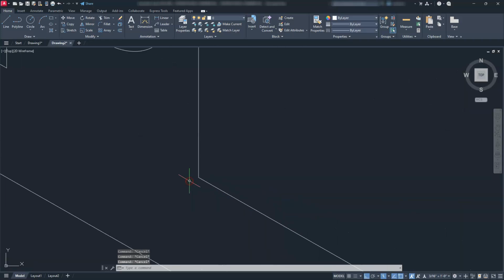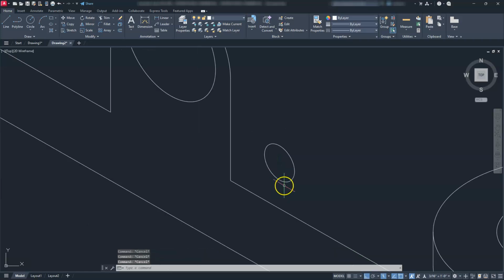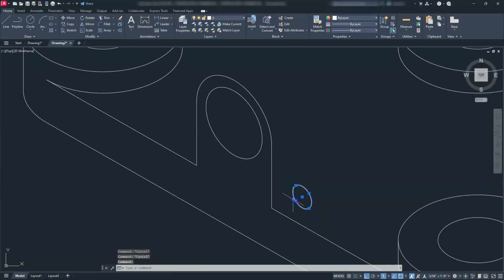Now we can't use the fillet command, so what I have to do is go to ellipse again, right? So EL, enter, iso circle. I'll type in whatever the radius is, which is going to be here, and this is at 5. Now I have 2 of these. So what I'm going to do is I'll select here, move it by that center grip, place it here. I'll select that center grip again, choose copy, and then I'll place it on that endpoint.